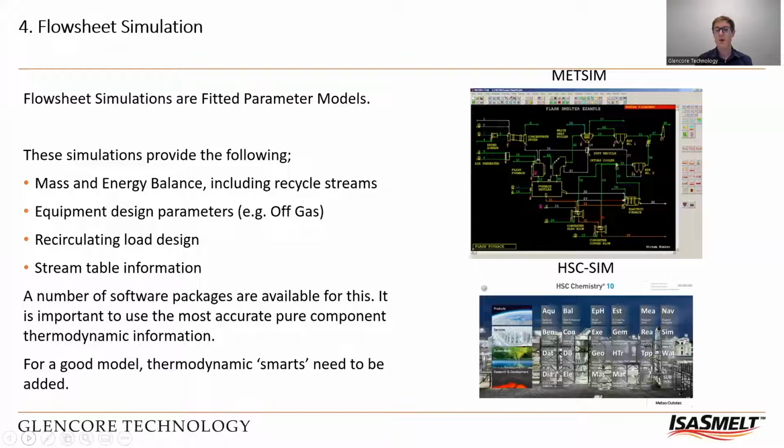So there's a number of software packages available. Both MetSim and HSC Sim are commonly used packages. The core backbone of these packages is their pure component thermodynamic information. So it's really important that you choose a package which has very accurate data and has really good reviews of the information. MetSim is an older package. Generally, if you use this package, you'll have to fill in the data and review a lot of the thermodynamic information, as a lot of the more modern information on the solutions and the component data is not quite accurate at times. And so instead we tend to use HSC Sim, as this has more accurate pure component data.